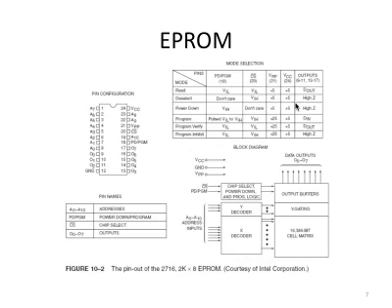Now in this slide, the bottom right figure shows the internal organization of this chip. There are some decoders, an X decoder and a Y decoder, used to decode the address, so that the address will be able to select one of the locations in the chip. And you have this 16,000-bit cell matrix. That is the transistor cell used to store the bits. Also, you have output buffers to drive the output.